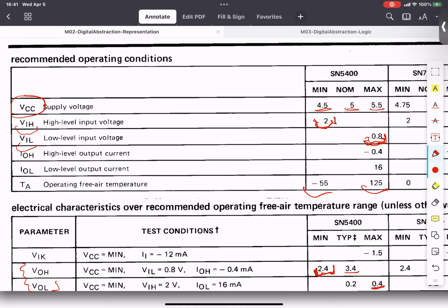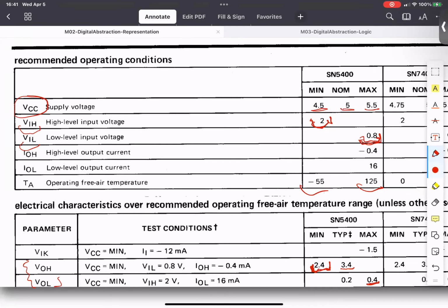Essentially, if I'm connecting lots of chips of this nature, I can look at VOH and VOL of the transmitter, and VIH and VIL of the receiver, and work out how much noise I can tolerate in the wires connecting the two and still work okay. The next stage will still correctly interpret 0 and 1. One can always go back to the data sheets and do this.